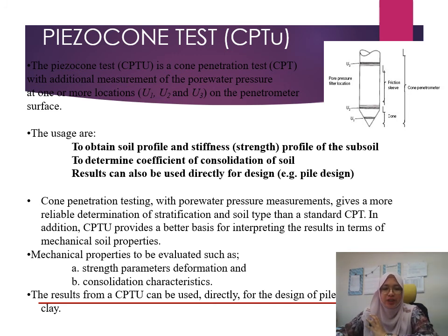It involves penetration with pore water measurement, giving more reliable determination of stratification and soil type compared to CPT. Mechanical properties can be evaluated, so soil parameters, deformation, and consolidation characteristics can be evaluated. The result from the piezo cone can be used directly for the design of pile foundation in clay soil.